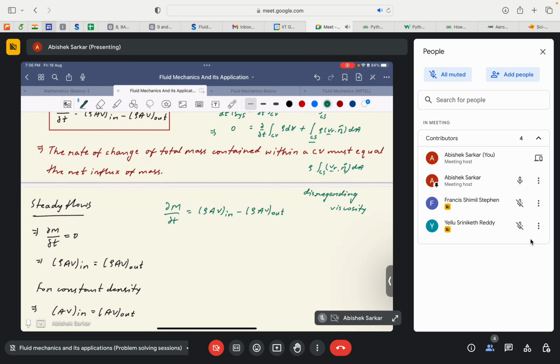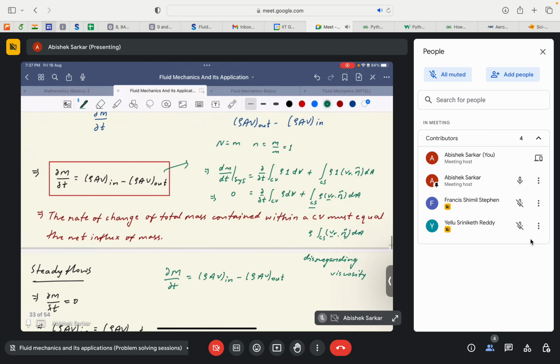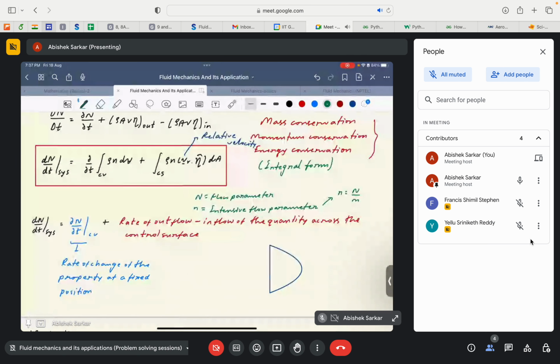If that's the case, then we can apply our Gauss divergence theorem here, and transform this integral into a volume integral. The right hand side of this equation, the RTT, would transform into the evaluation of volume integrals rather than regarding control volume and control surface separately. So that can be done, but there is no issue in having a control surface while considering the control volume or the Eulerian approach. This control surface should not be confused with the control system. I guess I was clear.